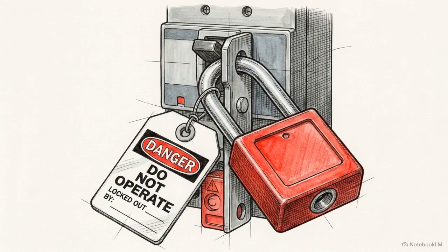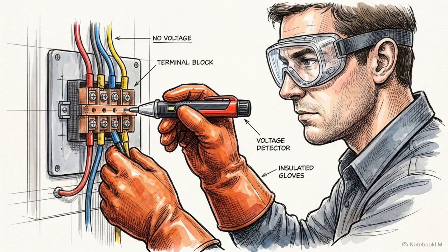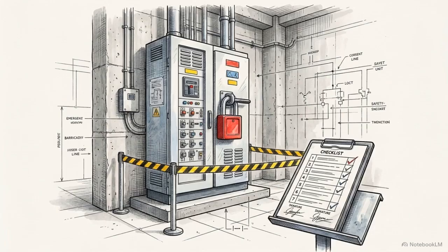Site preparation begins with a universal security protocol. The isolation mandate is absolute. You apply strict lockout and tagout controls, isolate the test boundary with safety warning tape, apply proper personal protective equipment, and install temporary grounds. You must visually confirm the total absence of any unintended live electrical exposure. Unwavering compliance with this preliminary paperwork and physical isolation creates the legally recognized foundation for field safety before physical testing begins.